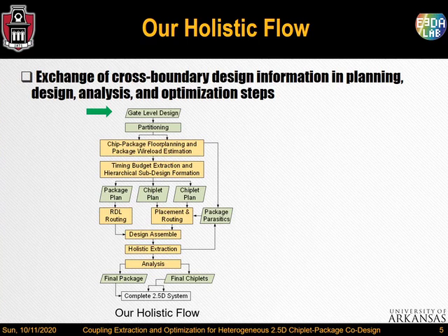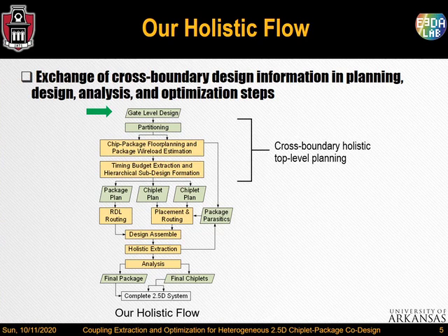Gate-level netlist is synthesized from the register transfer level description of the system. In the planning stage, partition and package planning are performed considering the complete system as a whole. The gate-level netlist is partitioned into chiplets considering the impacts of package wires on the partition result. In the co-planning step, chiplet pin configuration, package floor plan, and routings are prepared together.